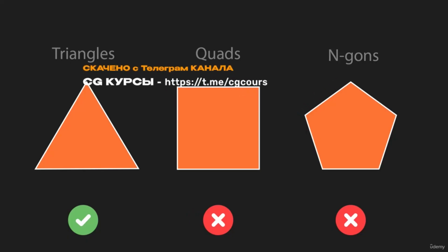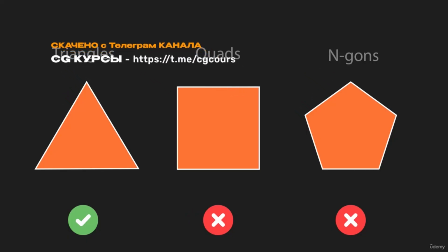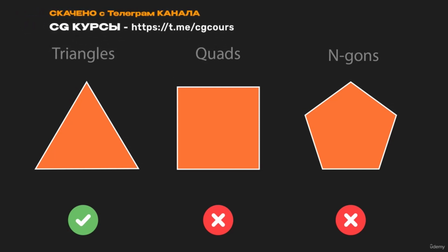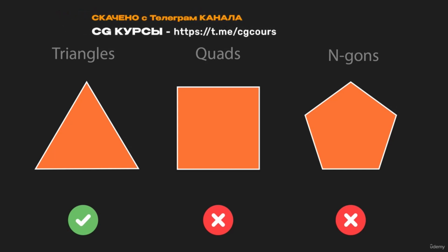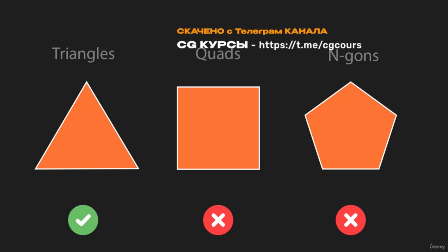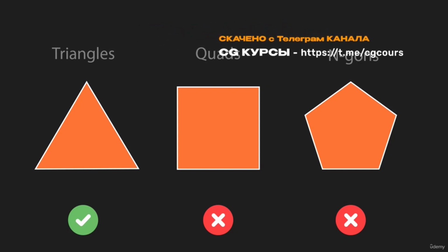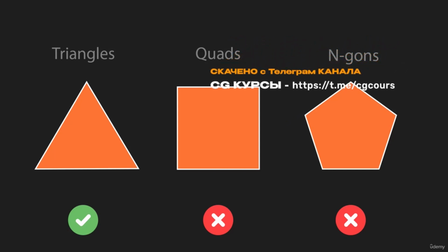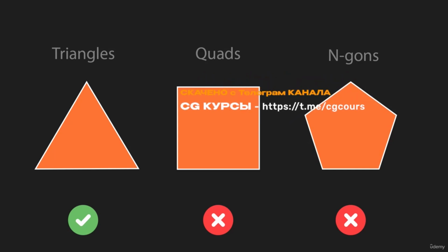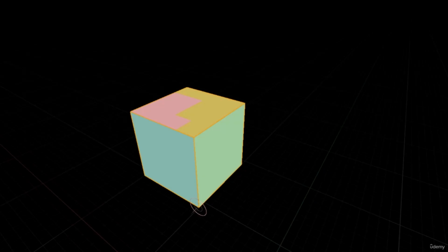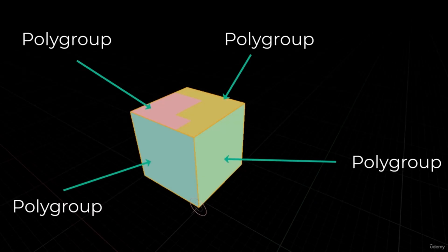The reason is Unreal Engine can't import a model that it can't render. Unreal Engine rendering is portable across all platforms, as all graphic drivers recognize triangles. Unreal Engine doesn't like to spend time and resources resolving quads and n-gons into triangles at runtime. That's why it converts all the meshes into triangles. So there is no concept of quad or n-gon, but it does support polygroups, and it's what I'm gonna explain in this lecture. Polygroups are a collection of triangles.